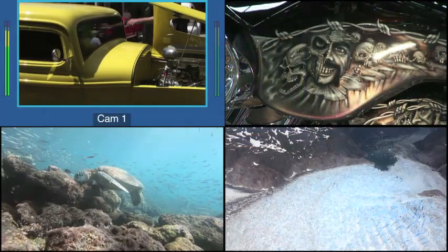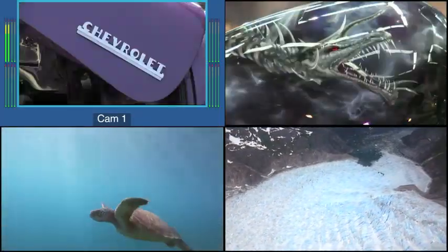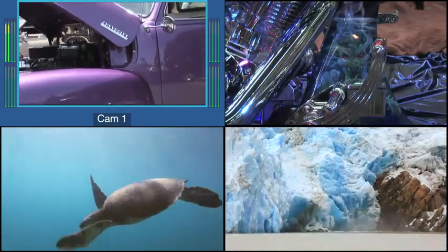We could have 2 groups, which would be the 8 channels display, or we could have all 4 groups, all 16 channels displayed alongside as well. Then it's asking, what is your reference level for the transition between the red and the yellow? And also the peak display, in terms of, okay, it'll tell us where the peak level is and how fast does that decay back to the individual audio meter. In this case, we'll leave it as slow.